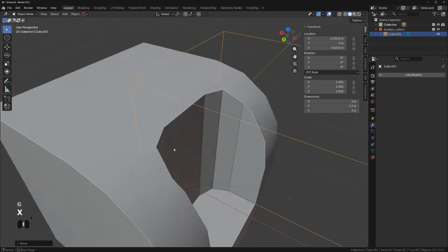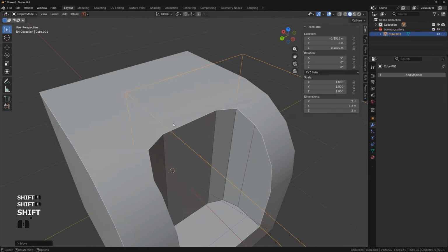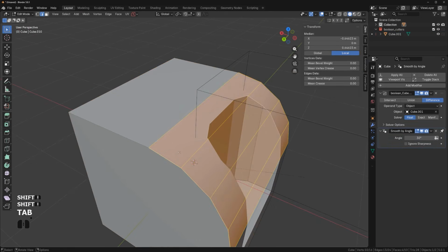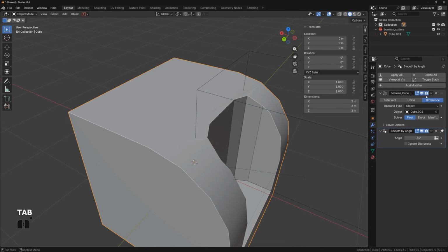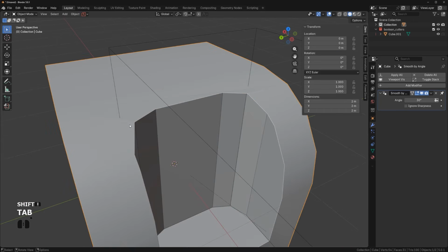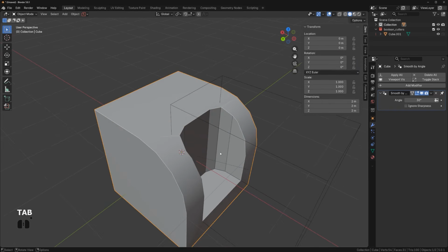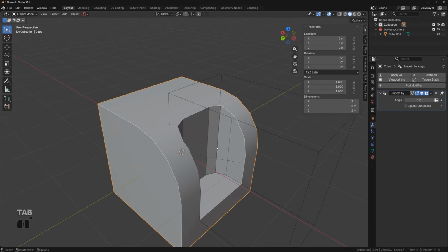You see how nasty the shading is that we're getting here, all these pools and lines. That's because these polygons became basically n-gons when I applied this boolean. They get bent. They're just simply too large, okay? So they get bent, which is why you get shading problems. And in order to fix this, you simply need denser topology.